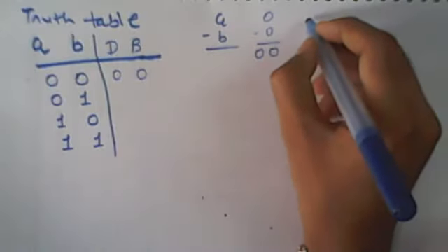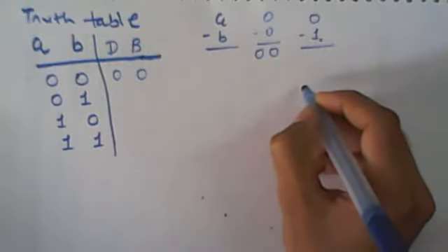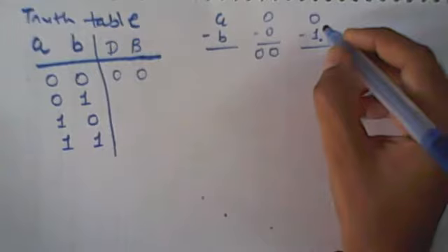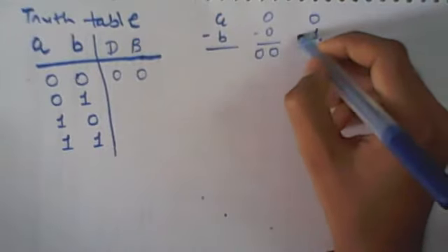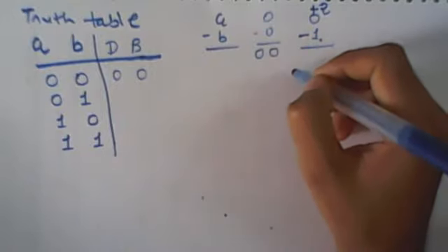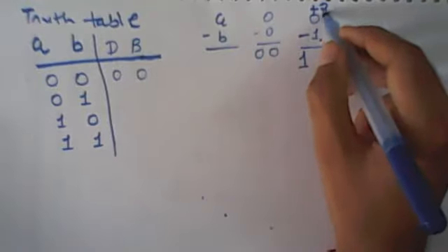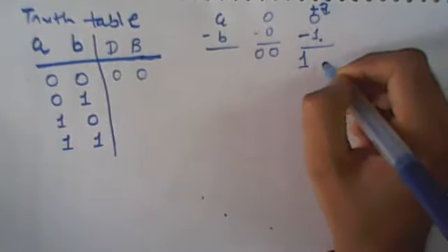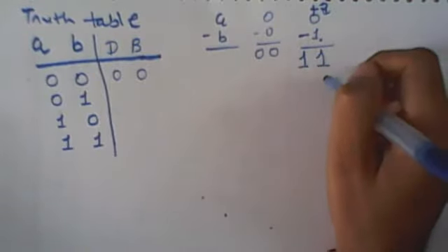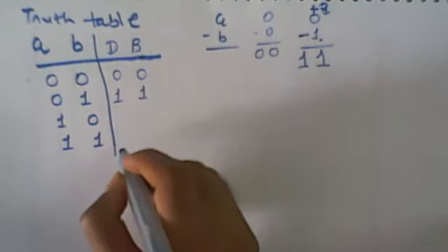If we want to subtract A equal to 0 and B equal to 1, 0 minus 1, then we need to take one borrow, right? So it is a binary subtraction, so the borrow value is 2. So its borrow is equal to 1. We took a borrow and the difference output is 2 minus 1, which is 1. So the difference bit is 1 and the borrow bit is also 1.